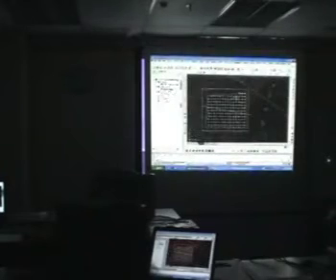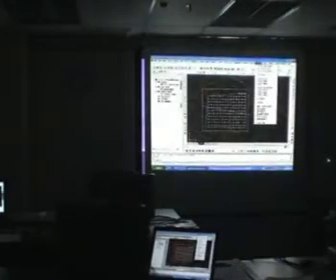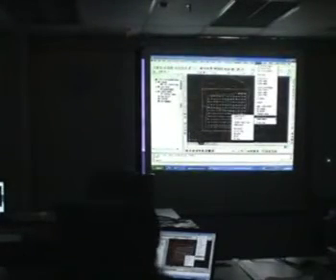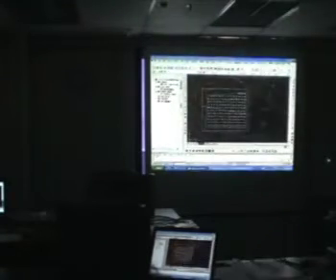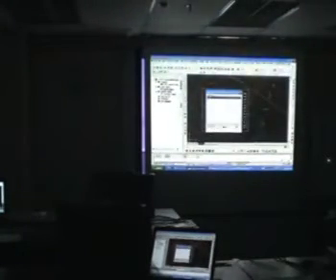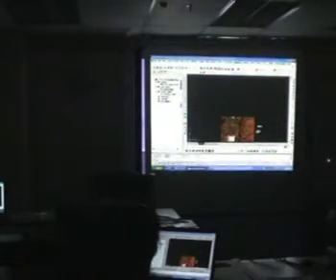So that's your grid volumes. For sections, if you need to generate any section drawings or section reports, you can click, say, plot all. I'm going to plot all the sections. I'm just going to put them somewhere here in the drawing, because what it's doing now is generating all the different sections. That's why it's blinking like mad.